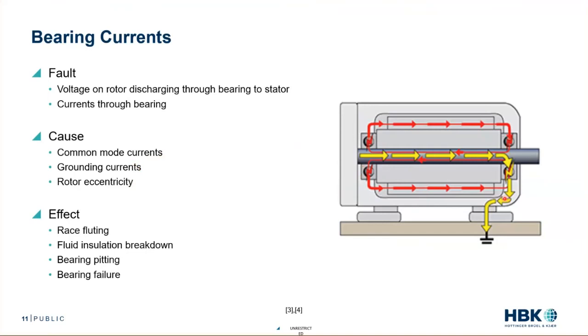Well, currents create heat. Heat creates problems. So I actually see fluting in the raceway of the bearing. If you look at a picture of a bearing with fluting on the raceway, there are little pits, and this is going to cause the bearing to not roll as well, or it's going to create flat parts and create bumping and more eccentricity. So we're going to cook that raceway and flute it.